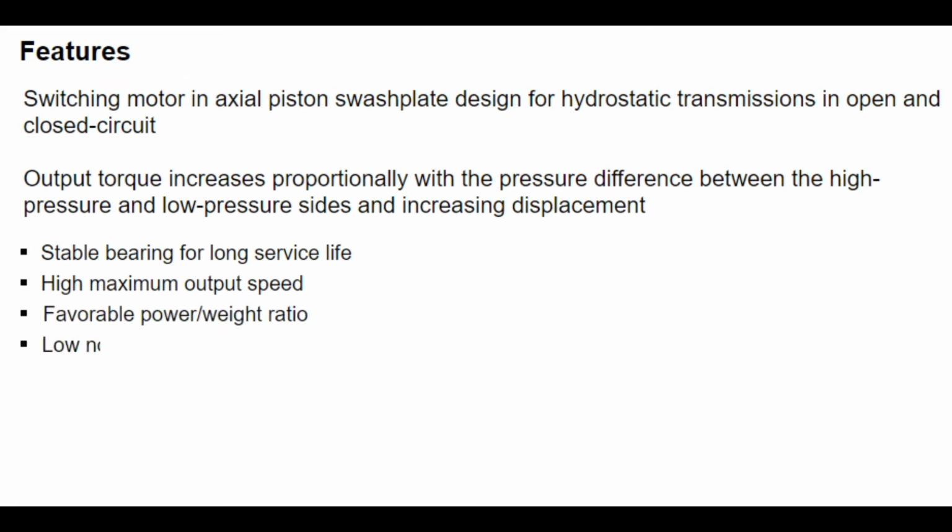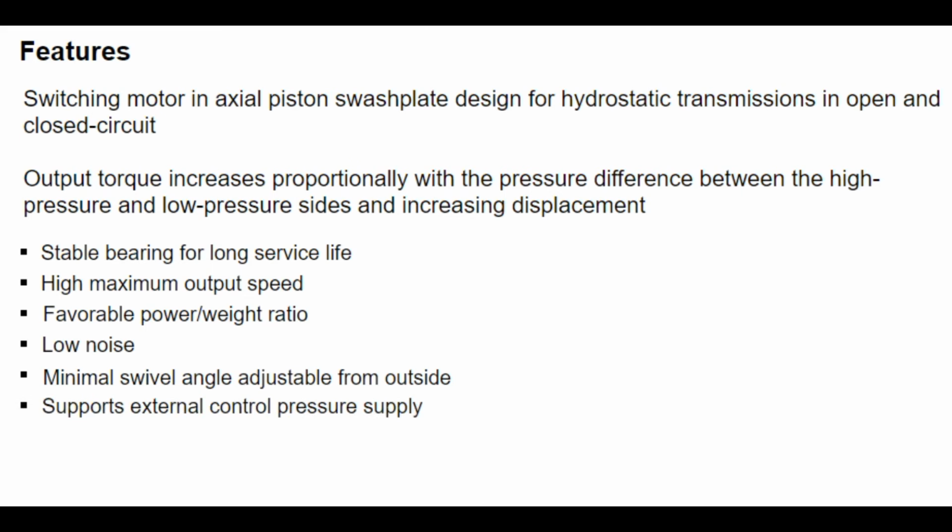The minimum swivel angle and thereby the maximum output speed can be adjusted from the outside. Two-point control can be directly actuated by an external control pressure supply, hydraulically or electrically by a solenoid switch.